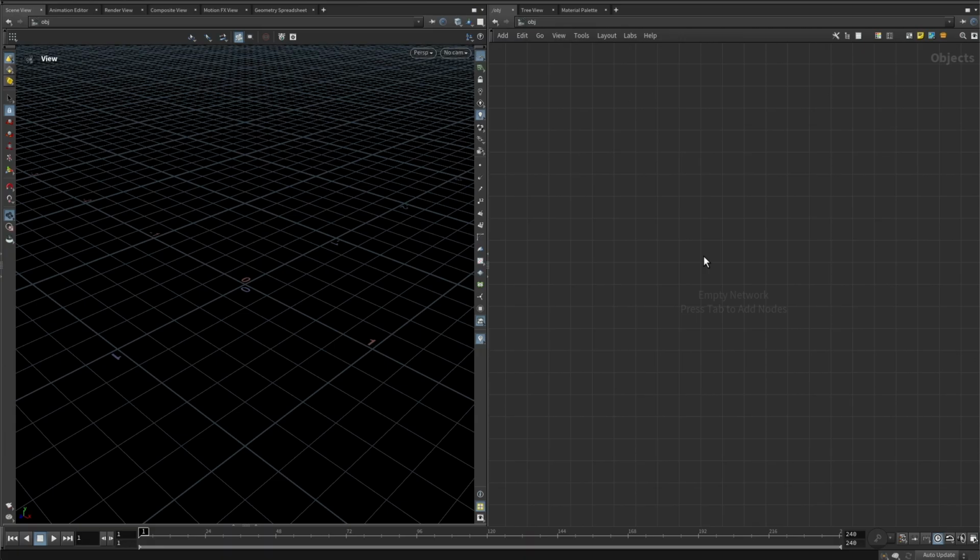And later on we will break the FLIP solver in Houdini and show you some nodes you can change and tweak for your liking. But for now, we'll just go basics to show you how the anatomy of the FLIP solver is in its basic form. So let's jump in by creating a geometry node in here.